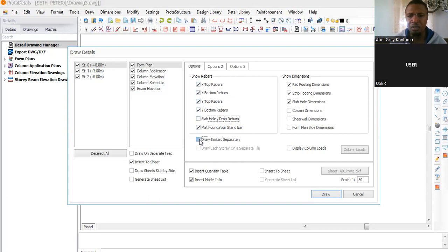Okay, so when you have a structural member that is actually similar, like I told you, just like when you have in your bar mark, where you have the same or a similar reinforcement, when the reinforcements are the same in shape, in size, in length, when you are doing your schedule, it will actually give you the same bar mark.